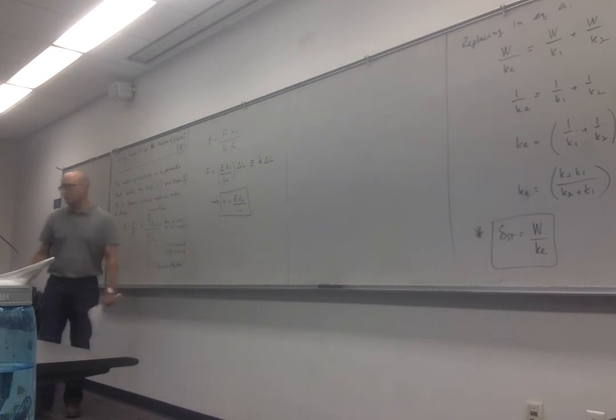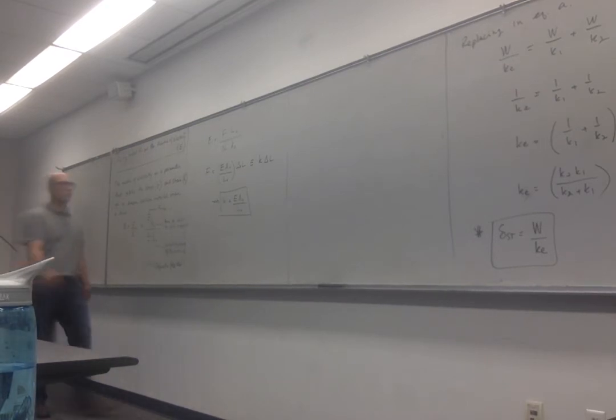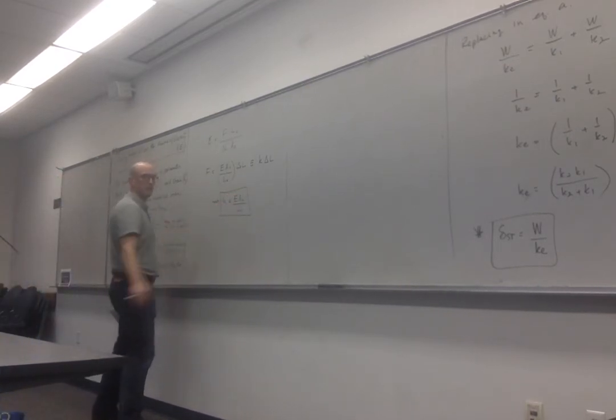So if you go in the lab, and you did some calculation, and you want a certain stiffness of the cushion, a certain K-value, then you can go and cut the cushion size you think you need. If you know its modulus of elasticity, you will know what thickness and area you will need.